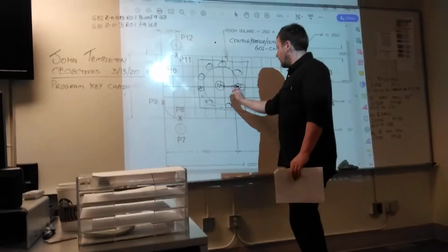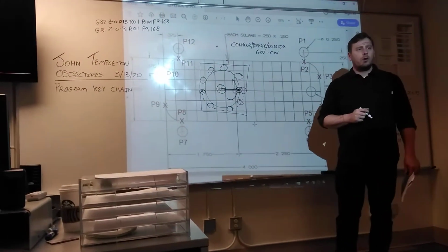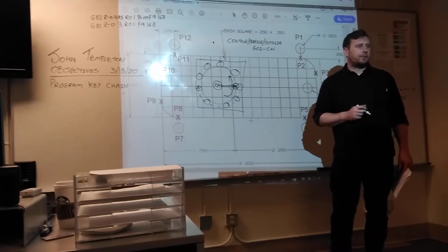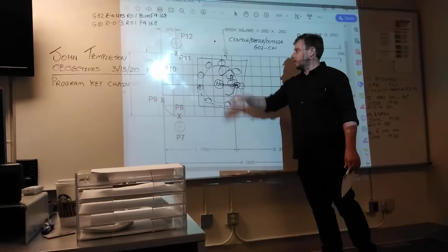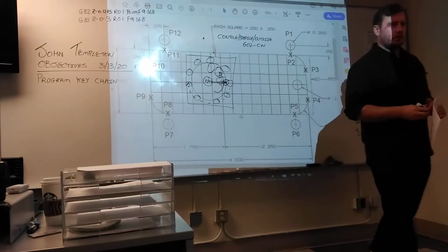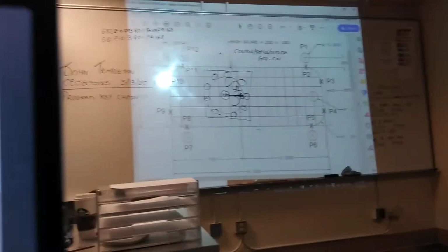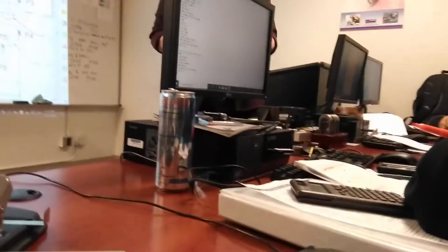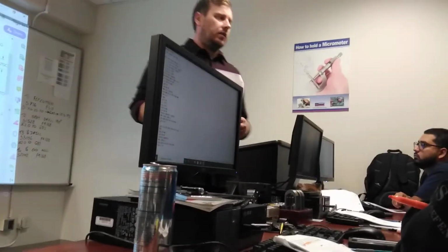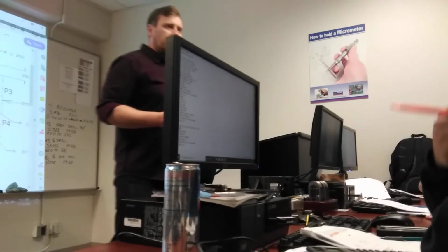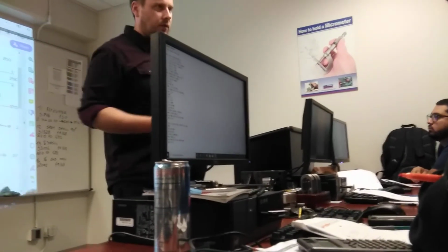But if you change the direction and now you go that direction, where's the tool going to move this time? Inside. That's exactly what you want the machine to do. It is critical you understand which way you're moving the tool. Left and right. It's a big difference depending on the direction that you're facing. This is my left hand. To you it looks like right.